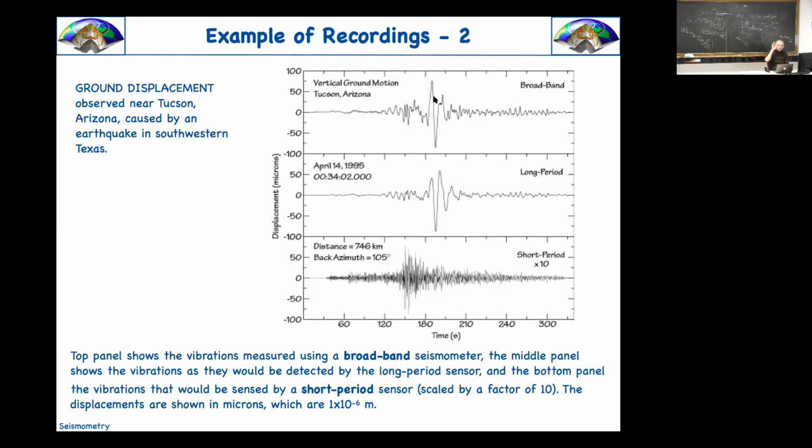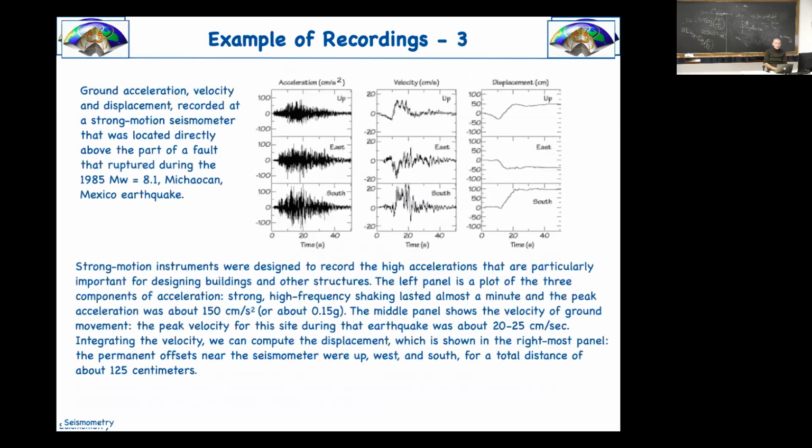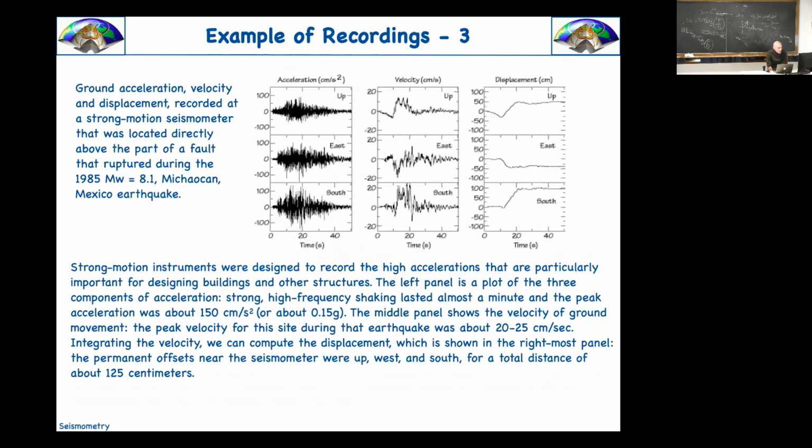But please remember that what you observe in a broadband can be filtered, and you may take the classical vision of long period and short period. Now look how different they appear. They are the same signal as in the broadband, but when you filter it, imagining to work with traditional long period and short period instruments, they are totally different. Look at the frequency content here, but also the amplitude, because this has been magnified by 10 times. So please remember this.